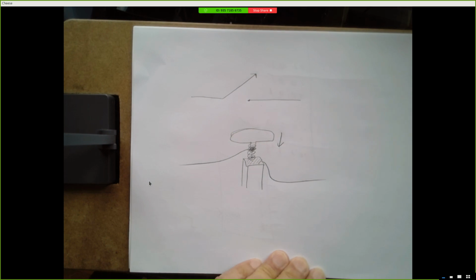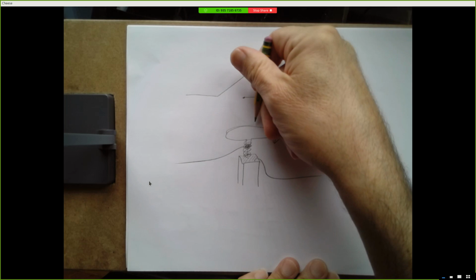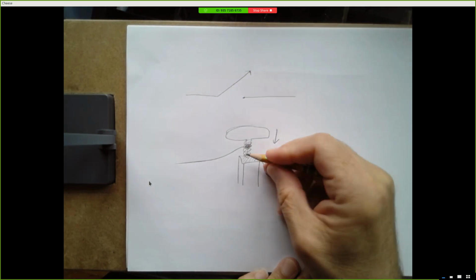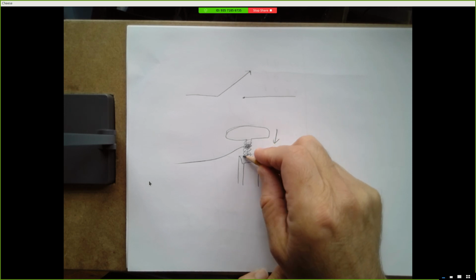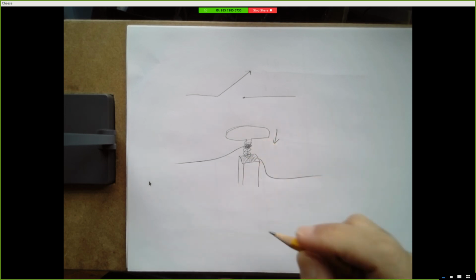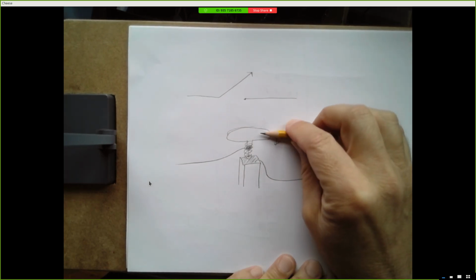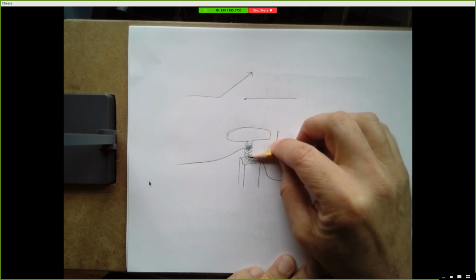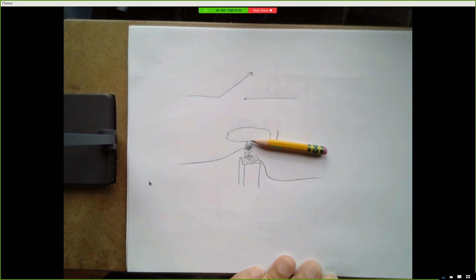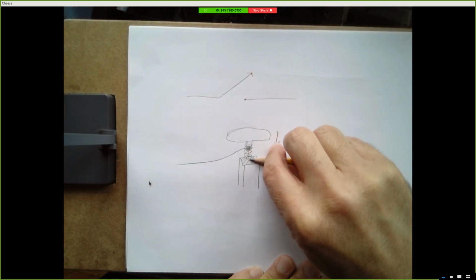But think about what's happening when you have a mechanical universe, right? As you apply pressure on this push button, the spring compresses, this piece of metal comes down, and eventually it touches this plate. Well, when it touches that plate, what's going to happen? It's going to bounce back a little bit. And if you put on just enough pressure to just barely make contact, the bounce from that, coupled with the spring, is going to cause it to lift up a little bit, and it's going to break the contact. Now, if you keep applying force downward, it will come back and it will make contact again.